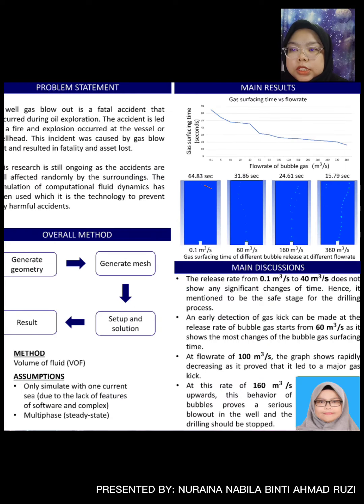As a conclusion, the increase of the inflow rate of the bubble gas led to a shorter time for the bubble gas rising up. As an early detection of the gas kick, if the bubble distribution starts to rise up faster and rapidly, the drilling should be stopped. From my simulation, it can be observed in only 1 meter height before the bubble is dissolved fully.